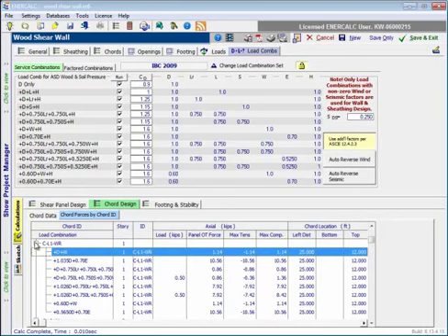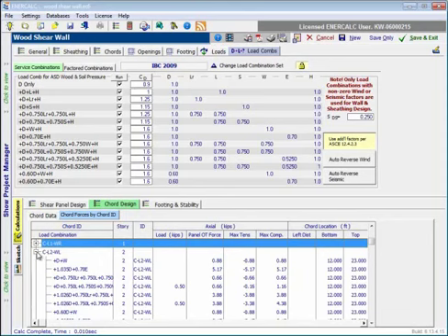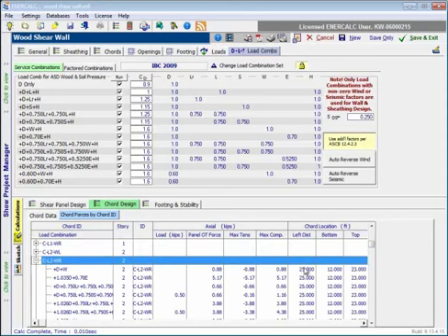And then if I was to go up to something other than level 1, like if I come to level 2 wall right, we can see that it's also at 25 feet, but now we start to pick up some elevation as well. The bottom of this chord is at the 12-foot elevation, the top of this chord is at the 23-foot elevation. So that's the information presented on the chord forces by chord ID subtab.